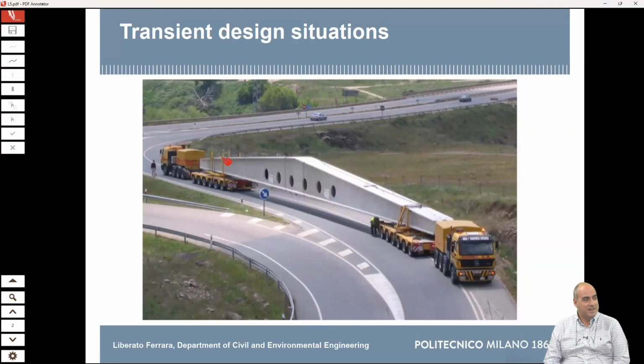Yes, exactly. The issue is that when you curve, the beam will experience some kind of torsion, accompanied also by some tilting effect, which tends to bend it in the minor stiffness axis. So you have to block also those deformations in order for the beam to be stable.